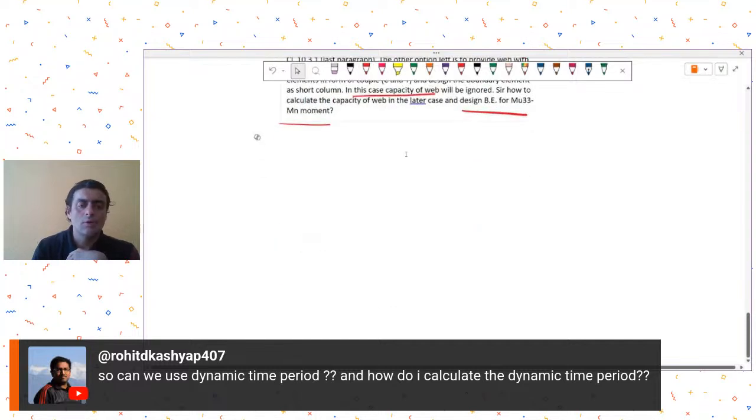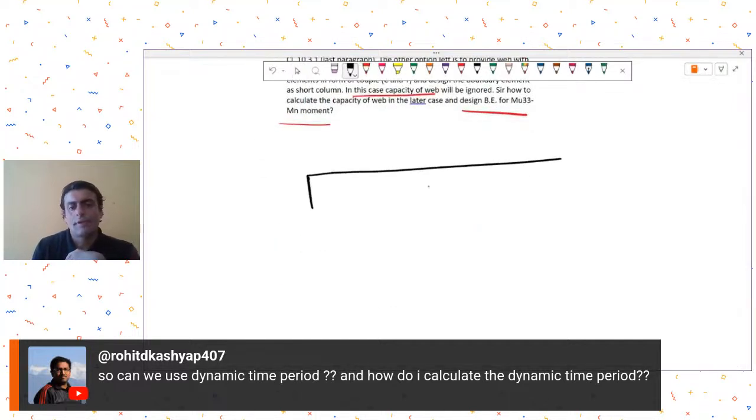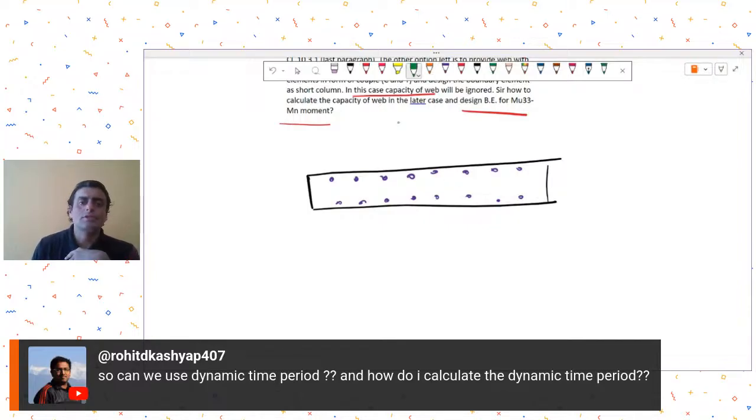So see what your code is trying to tell you, that the annexure A of IS 1893 has been provided to you for a reinforcement distribution like this. That is the core concept that you need to understand. So this is how the reinforcement is distributed uniformly about the minor axis, and you don't have any reinforcement distribution, let's say, about the major axis, you do not have any column like reinforcement distribution. So your reinforcement distribution is about the minor axis as shown.